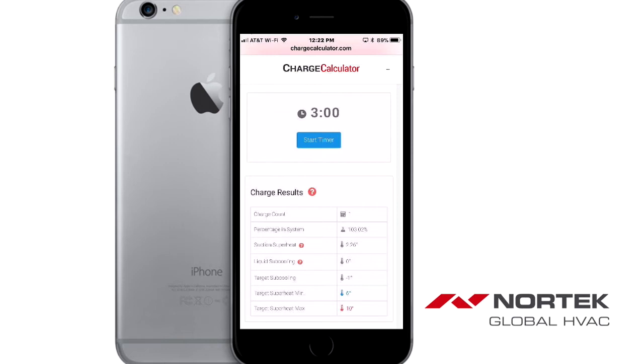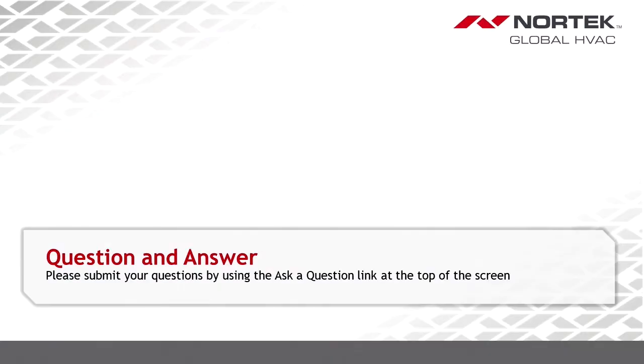It's going to give you kind of what I like to think of, for me, I can visualize based on those numbers where that superheat and subcooling is at. So, you know, I think it'll be a beneficial tool for everybody out there. We would recommend, as always, using it in the cooling mode, but this allows you to use it in cooler temperatures and lets you use it in the heating mode on the heat pump side.